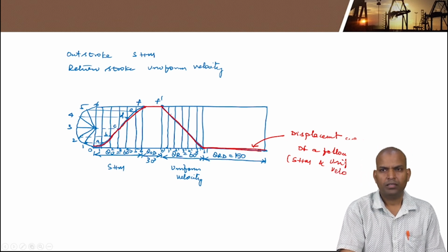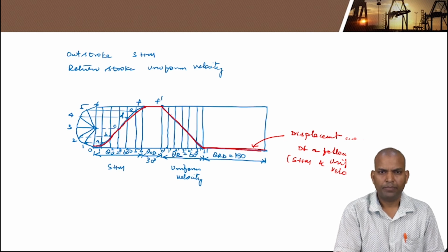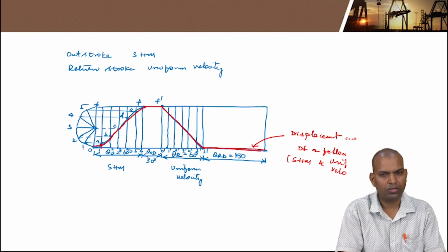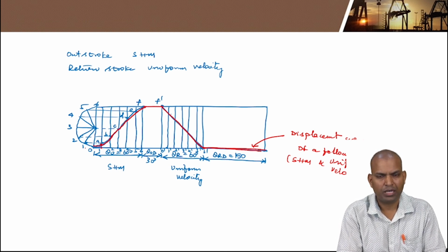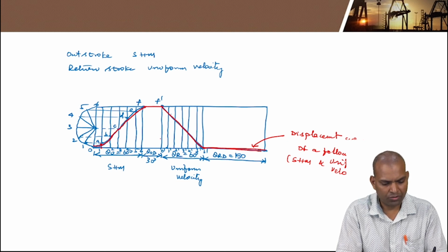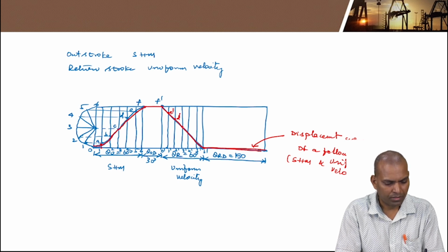Okay. In this manner we can draw, and the remaining procedure is the same, but we have to consider the displacement while marking on the tangential lines passing from the offset circle to the points of the base circle. On those points you have to consider these distances: F dash, E dash, D dash, C dash, B dash, A dash.